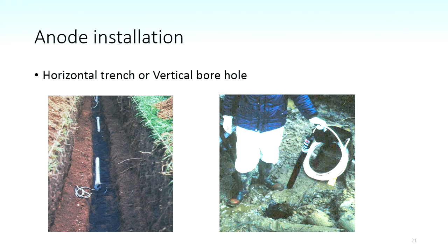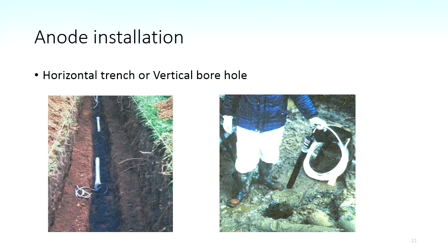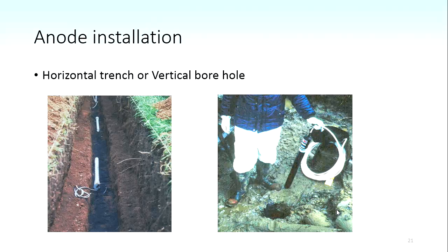As you might imagine, in terms of labour, it's a little bit easier to bore a vertical hole than to dig a long trench. And of course, if you're in an urban environment, the chances of being allowed to dig a long trench are slim, so it's advantageous to dig selective holes with a borer. So there are various reasons why you might choose one or the other option. And again, you can backfill part of this borehole with conductive medium.